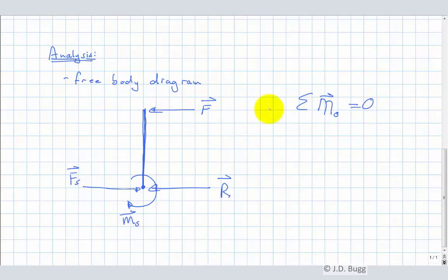So, like we said when we introduced the free body diagram, there are two things contributing to this moment. The moment of the fluid pushing on the surface, plus the moment due to this force at the top. And I'm going to represent that moment by R cross F. And those have to add up to 0. So the R here is the position vector to where that force is applied. So we'll talk about what that is later on when we get to it.